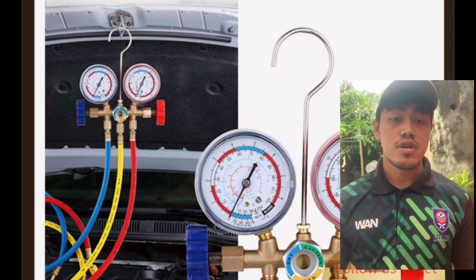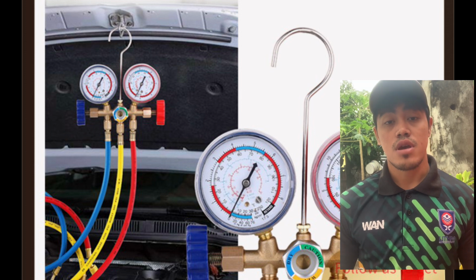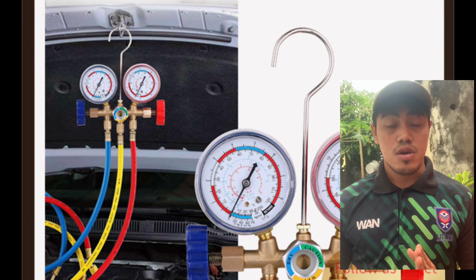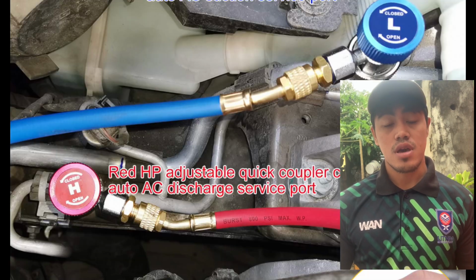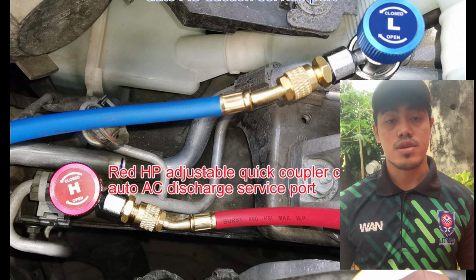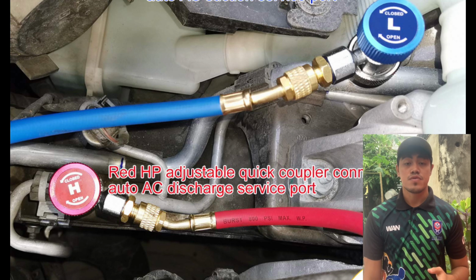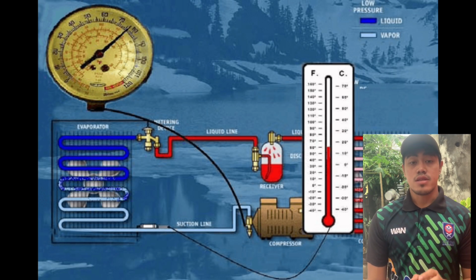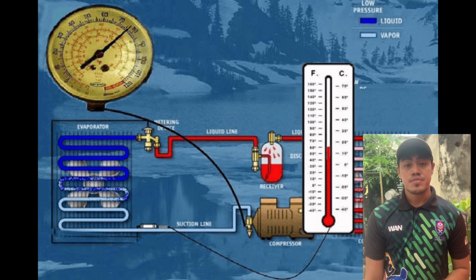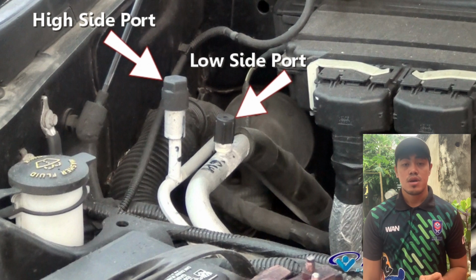And then after filling the refrigerant into the system properly and fully, both of the two hose valves, which are the red and blue hose valves, must be closed. After closing the blue and red color hose valves, disconnect the refrigerant valve from the center hose of the manifold, and reinstall the port cap. After that,